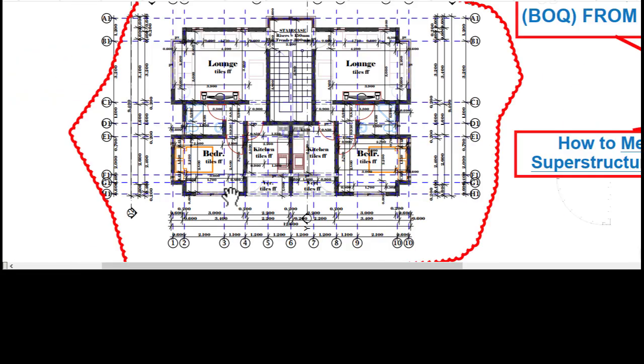Okay, so that means at grid 4, our wall is starting from F1, the internal wall, all the way to D1. So that is the length that we are going to measure. And looking at this, you can see the length has been indicated, coming from this point where my cursor is, then moving all the way up, and this is 2.5 meters. Okay, so we also indicate this to be 2.5 meters, and then we move on to the next bit of it.